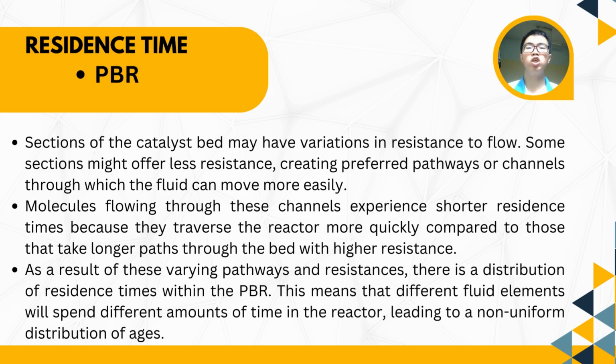In a PFR, sections of the catalytic bed may have variations in resistance to flow. Some sections might offer less resistance, creating a preferred pathway or channel through which the fluid can move more easily. Molecules flowing through this channel experience shorter residence time because they traverse the reactor more quickly compared to those that take a longer path through the bed with a higher resistance.